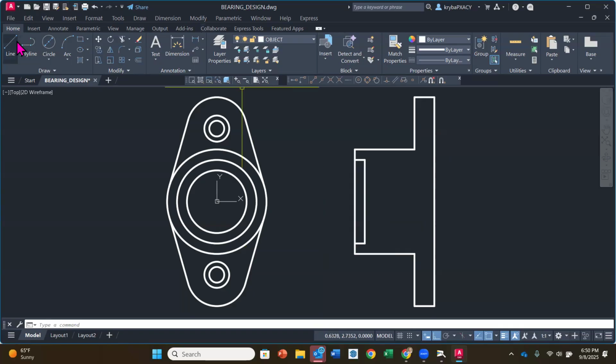Okay, so I'm going to do my line. So my inside hole is that 1.5 inch. I'm going to activate that quadrant. And now this way I can go to the bottom of the counter bore to start my line. That's where I would avoid a trim. And then I'm going to go straight through the part to the other side. Now I'm going to do that very same thing at the bottom. Another line, activate that quadrant, go over, over, over, click when I get to the bottom of that counter bore, and then click when I get to the bottom of the part. Okay.